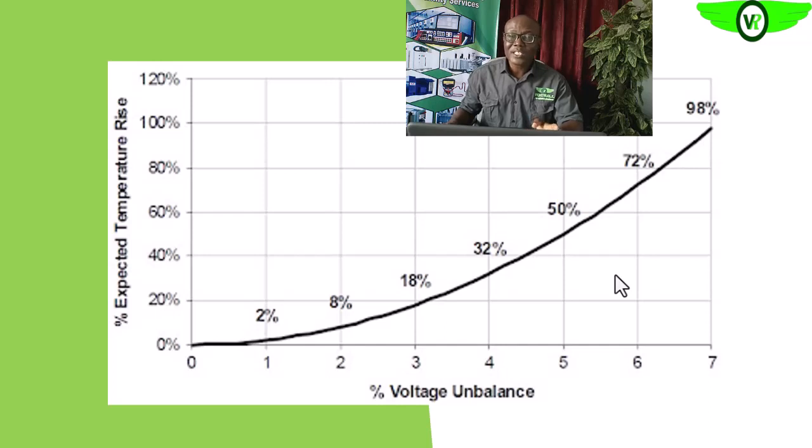So you check the unbalance at the input into the motor system. That is the input into your circuit breaker or into your fuses at the MCC, and then the input into your motor at the terminal block of the electric motor.